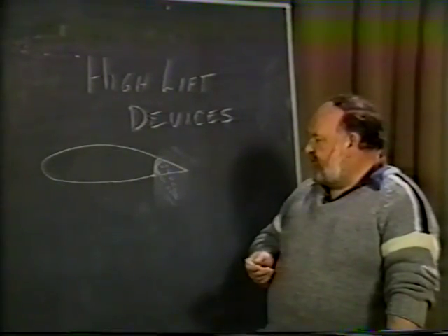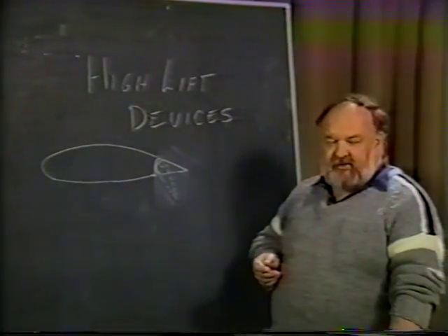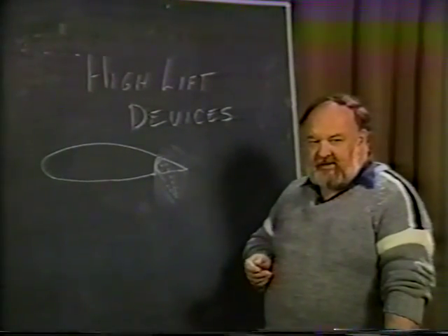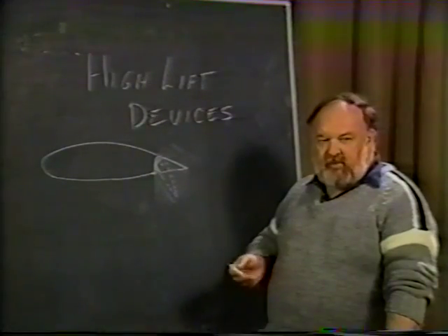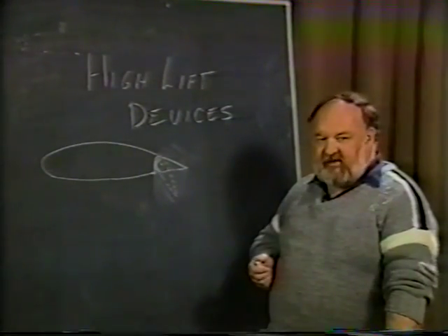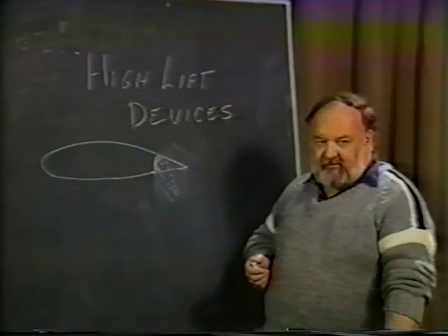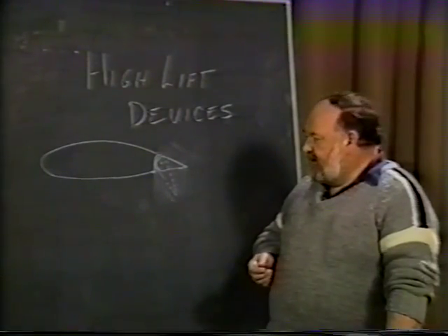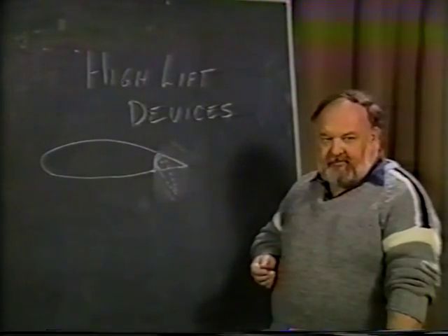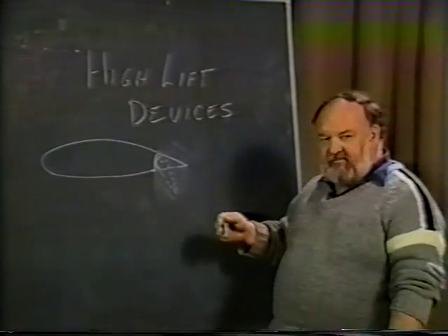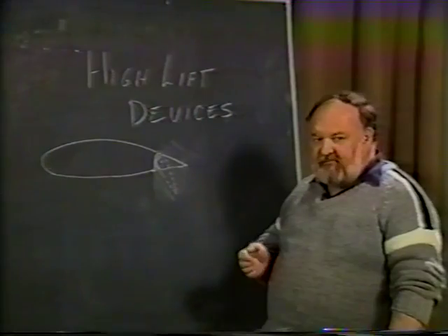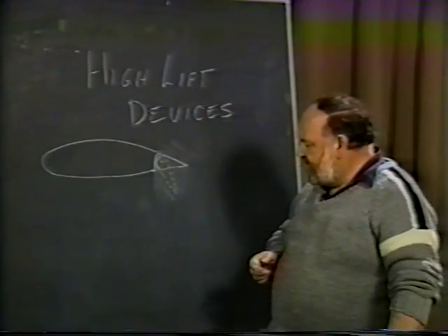You have a hinge point inside the wing itself, so you do not have any external brackets or anything like this. The load on the flap, the hinge moment load, so therefore the load of activating it, whether it's electrical, hydraulic, or just manual, is a little bit higher than a split flap, but not too bad. Obviously, the length of the chord of any of these flaps controls the amount of lift. We can go into that in a little more detail later.